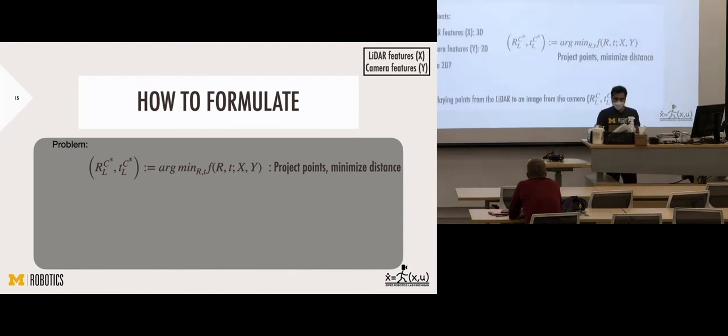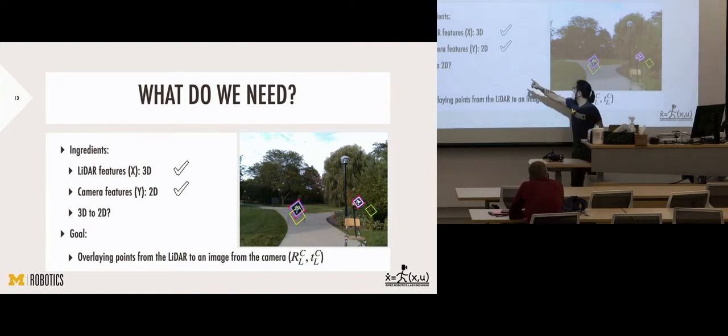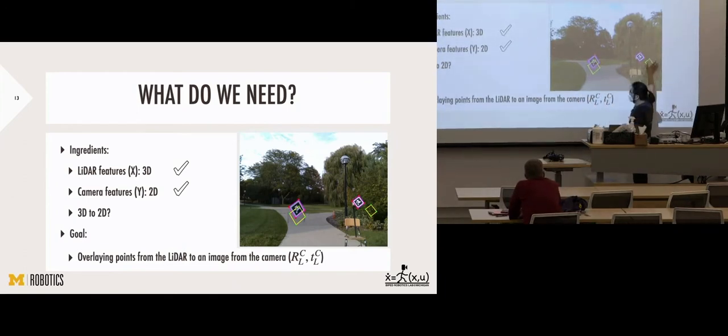So visually, imagine this is the camera corners, right? We have these camera corners treated as y, like this. And we have these yellow-green points. Those are the projected LiDAR vertices on the image plane. What we want to do is minimize the distance like this. Imagine we have the association, so we know which corner corresponds to which. We want to minimize it. So that's the high-level idea.